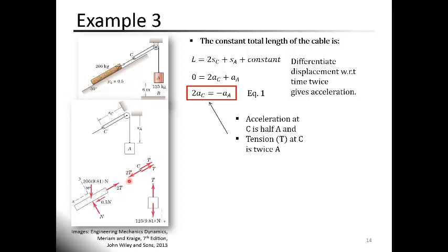So in turn, the tension in this part of the cable here is 2T, because all the forces in the x direction are equal to 0, since it's balanced. So in this case, the tension here is 2T, and consequently, due to action and reaction, Newton's third law, we have on the log a force that is pulling the log up, which is 2T.